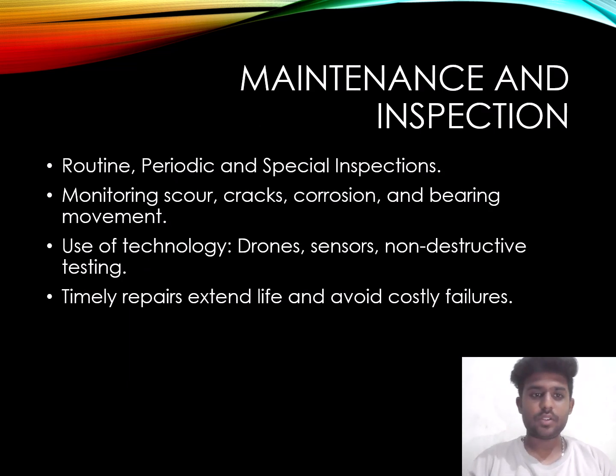Maintenance and inspection. Routine, periodic and special inspection, monitoring scour, cracks, corrosion and bearing movement, use of technology, drones, sensors, non-destructive testing, timely repairs extend life and avoid costly failures.